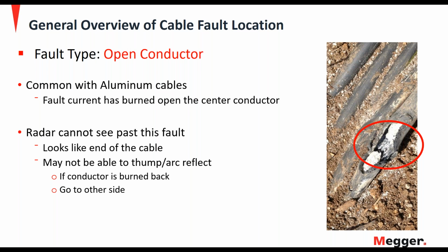And one of the things to note is this type of fault, it may be burned back from the source side, and it may not flash over very good. But on the other hand, it may flash over very easy from the load side.